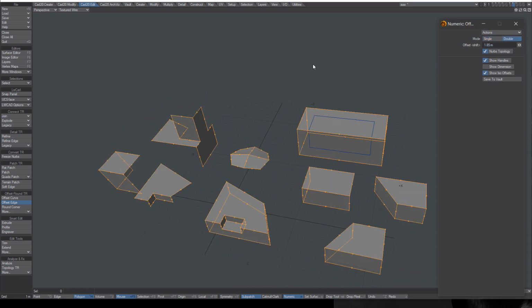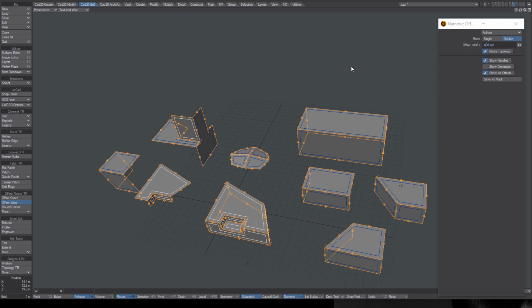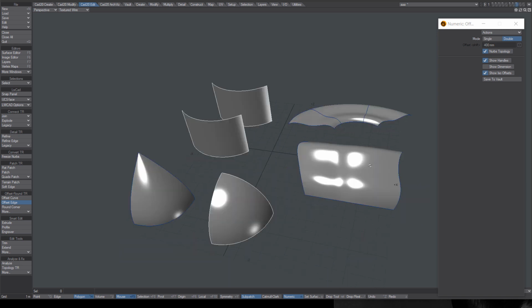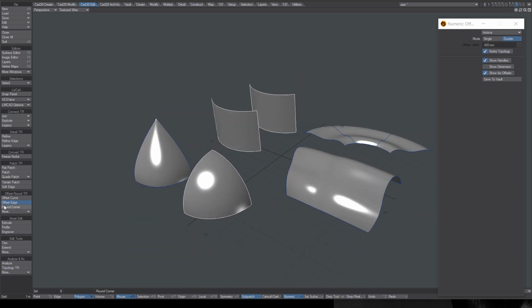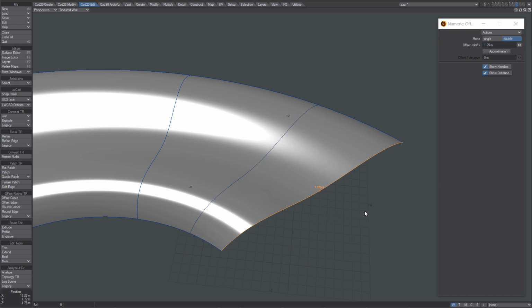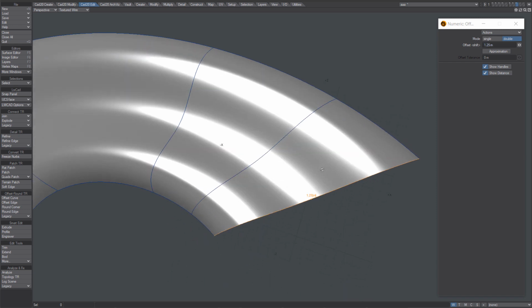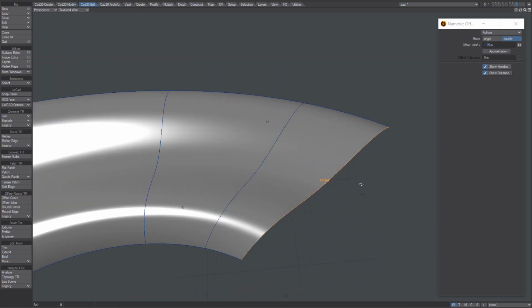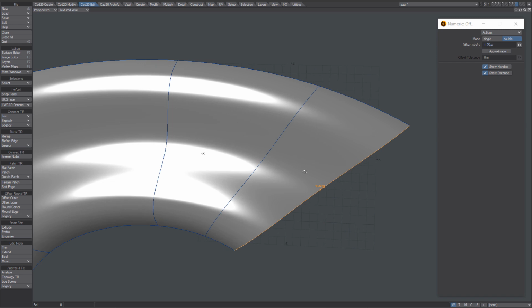So this is pretty much same offset tool as previous version, but the real change is on NURBS surfaces here. Here the offset edge works completely different than previous version. Previous version of offset tool, now offset legacy, was not actually doing offset operation correctly. It was just splitting NURBS surface into two pieces, and the offset on the beginning and end of the offset edge was just the average of the offset parameter. So for some irregular shapes, there was visible difference in offset on the beginning and end.